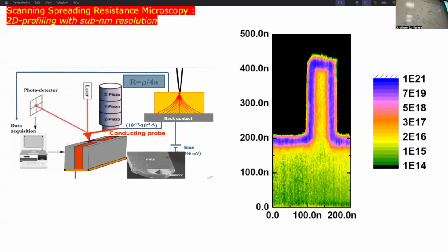And you can see how this is the gate, and you see it's highly conductive. And you see how the distribution of the dopants in the fin is almost uniform, right? So this is when you do your well doping, so this is the kind of thing you want to target. You want this kind of doping profile. This thing is 200 nanometer high.